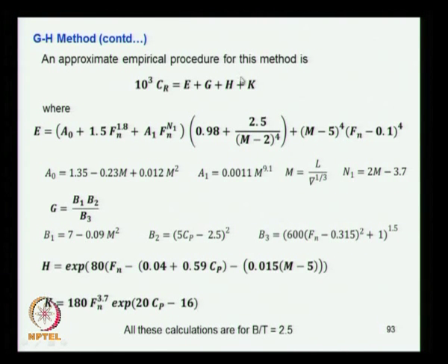So these values again, so you get the standard, that is as per the Goldhammer-Howard standard, the 10 cube Cr, that is the residuary resistance coefficient of the vessel which you are considering for the design. Whenever there is a deviation, of course the B by T assumed here is 2.5, that is the standard B by T assumed by Goldhammer-Howard. If the vessel which you consider for design deviates from this, you have to give a correction in 10 cube Cr for the B by T.